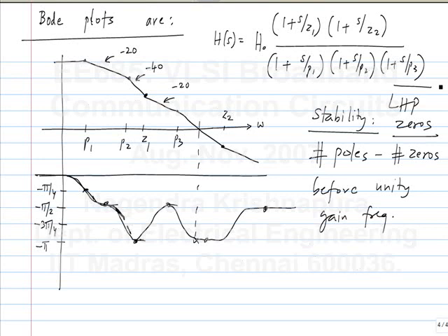When you have right half plane zeros, it will increase the magnitude response by plus 20 dB per decade, but it actually provides a phase lag. So that doesn't apply here. Because of the phase lag, you can have instability, and it may not have reached the magnitude crossing. So when we say number of poles minus zeros, we assume that all poles and zeros are in the left half plane, and of course, that the poles and zeros are real. So it is an approximation of that.